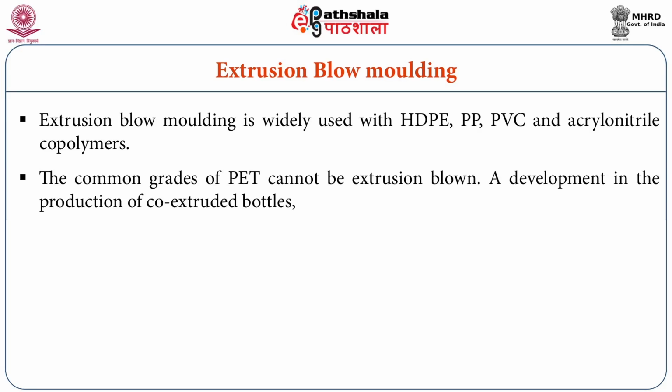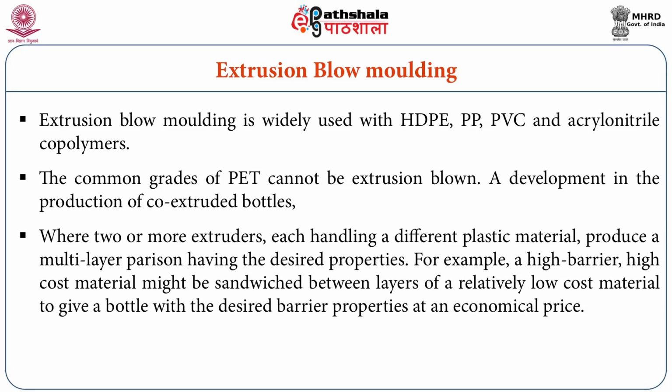A development in the production of co-extruded bottles uses two or more extruders, each handling a different plastic material, to produce a multi-layer parison having the desired properties. For example, a high barrier, high cost material might be sandwiched between layers of relatively low cost material to give a bottle with the desired barrier properties at an economical price.